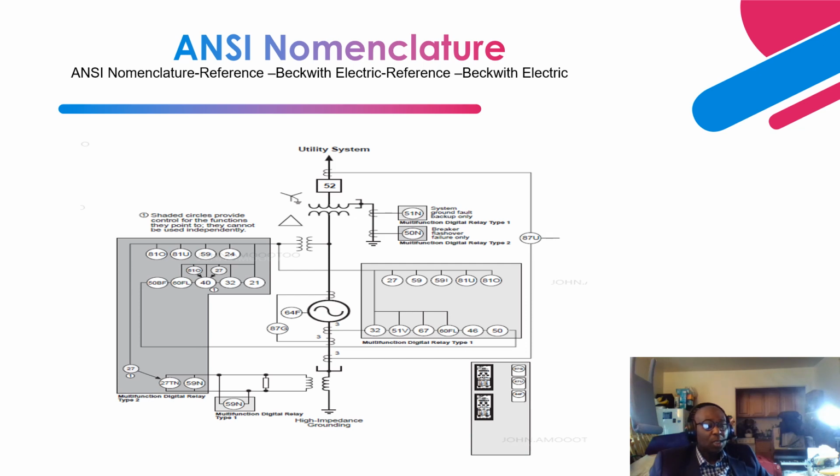Next is 27. 27 is an undervoltage relay. Let's say you have a heavily loaded generator, and the voltage is going to go down, or there is inaccurate sensing of voltage. This is when this relay picks up and trips the required breakers.